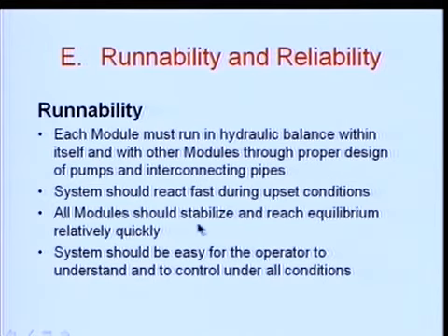All modules should restabilize and reach equilibrium relatively quickly. Now what does that mean? Basically that you must reach steady state condition very, very fast. You can't have screening system all ready to go and flotation system is not ready to go because it has not reached a steady state. Now that's an upset condition and you should not have a design like that.